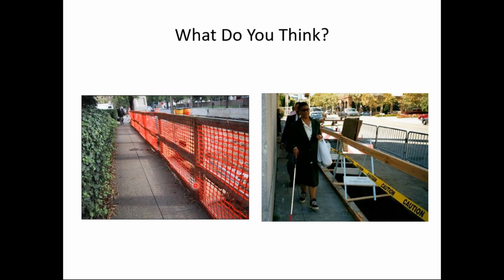edging or barricade. One thing to be careful about with this netting here is that if it becomes loose and starts to sag, a cane can get caught in there, and that can be an issue. So if you're going to use that, make sure that you check the tension or the tautness of that netting. Then how about this one here on the right? We have a wall here. This does not appear to be 6 inches in height. So to me, that is not an appropriate pedestrian edge.